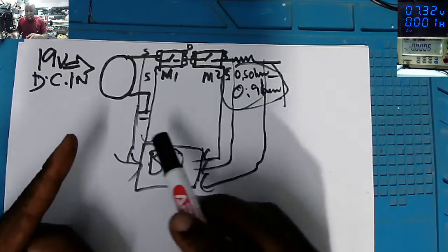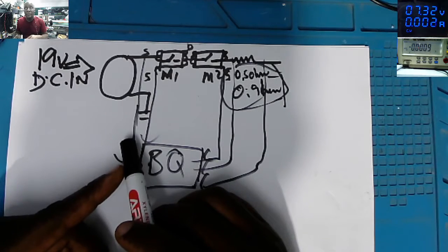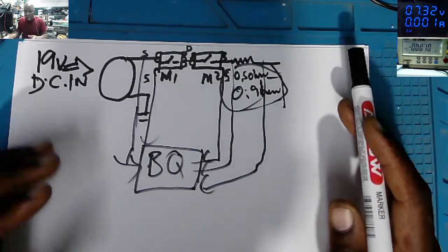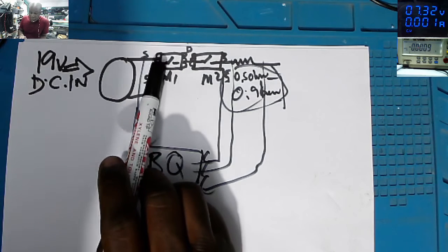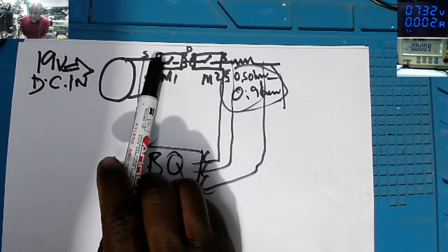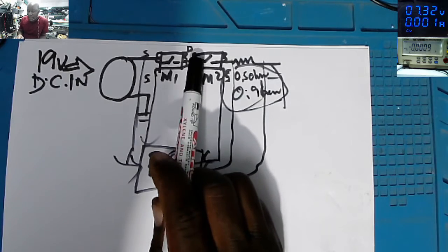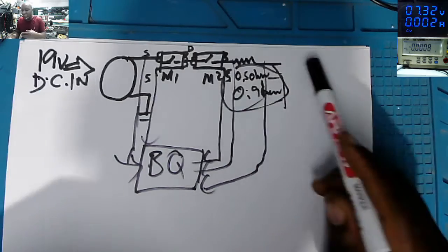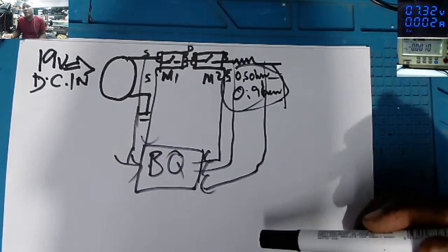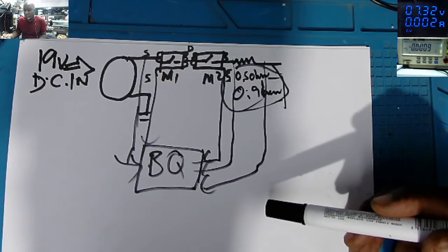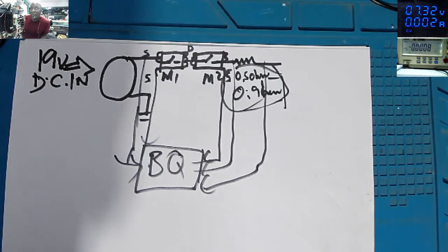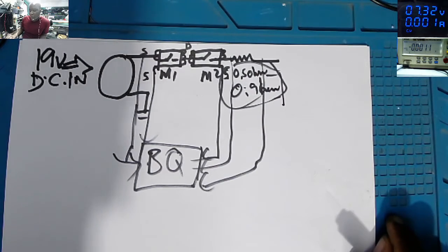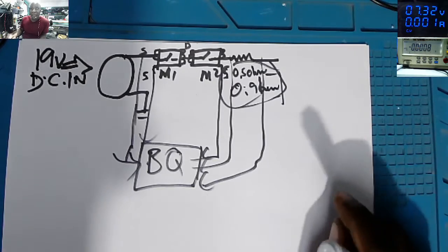So when you plug in the charger to the charging port, you have a dead laptop motherboard. You check on the input, you have 19 volts. Output of the second MOSFET, probably you don't have any voltage. You have to understand a few things. Why is this MOSFET not driving power? Maybe we have a shorted power rail, or maybe the MOSFET is faulty, or it can be anything in electronics.